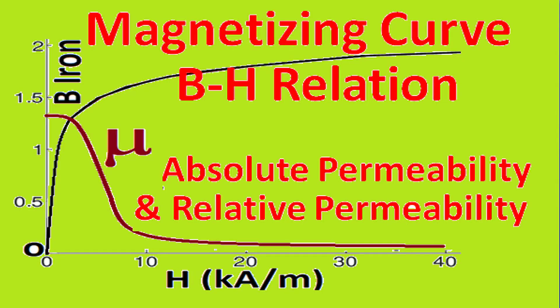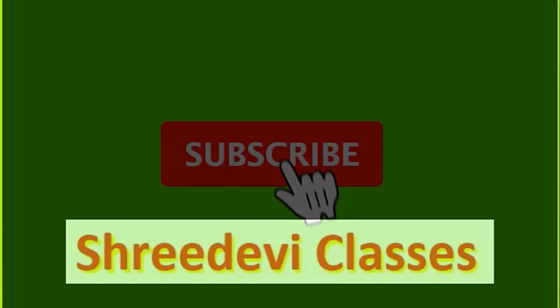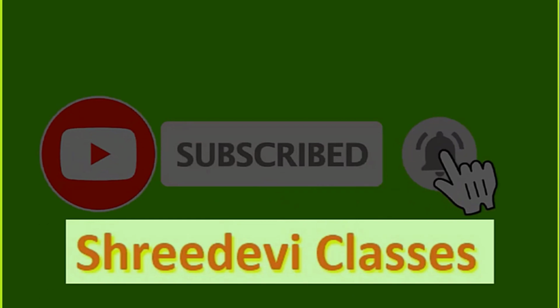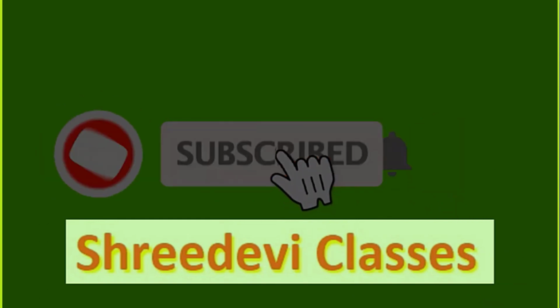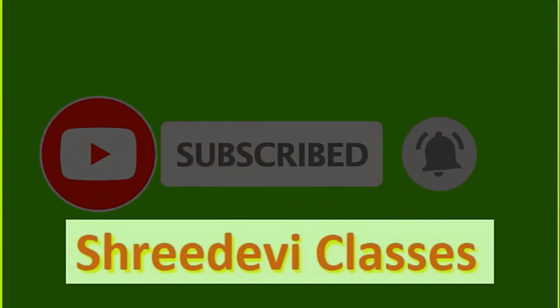We hope this interesting and informative video has explained the magnetizing curve of ferromagnetic material, and now you could understand that when applied magnetic field intensity is increased, first tilting of the easy domain takes place, then during tilting of the difficult domain the slope of the BH relation decreases, which results in a decrease in dynamic or relative permeability, and after deep saturation, magnetic induction becomes almost constant even with an increase of applied magnetic field intensity.